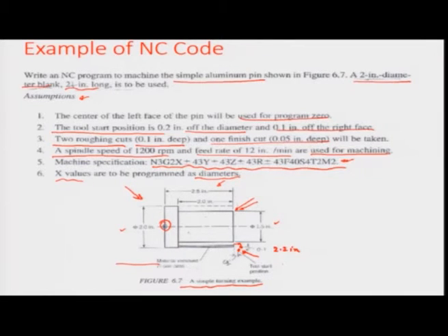Okay. So, as you remember that in this particular case the z axis is along this direction. So, this is the positive z, where the cutting edge of the tool, which is probably starting somewhere here. Okay, it has to start somewhere here because it is a single point cutting tool obviously. So, it will have to go parallel to the axis after it has gotten a certain depth into the workpiece. So, the depth can be in this direction and parallel to the axis is in the minus z direction. Minus z corresponds to the tool approaching the workpiece.